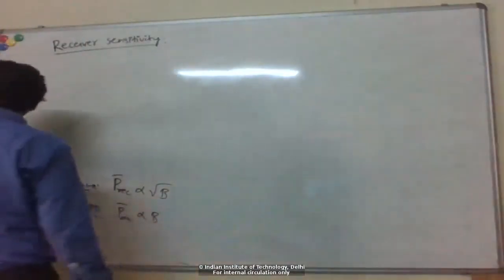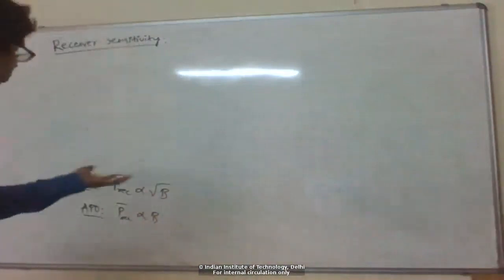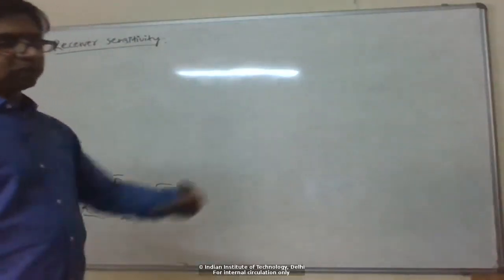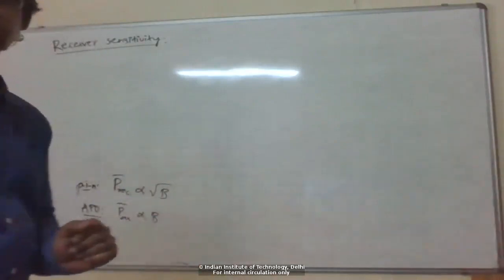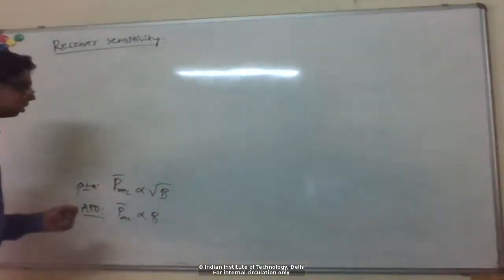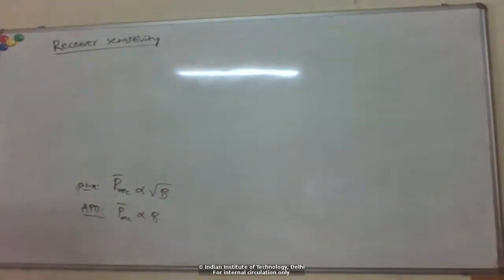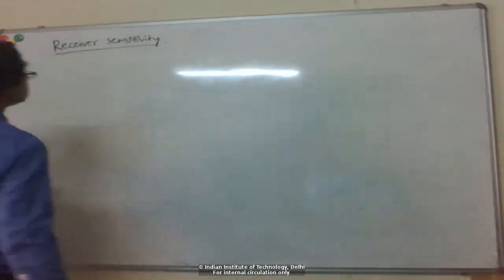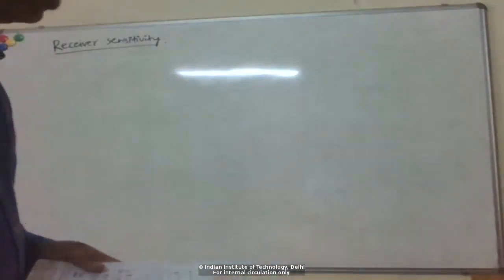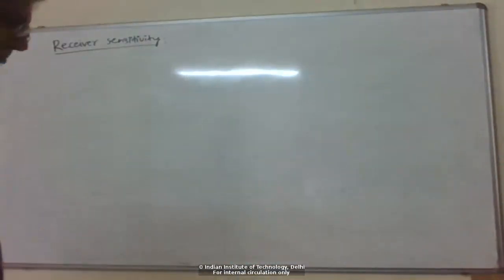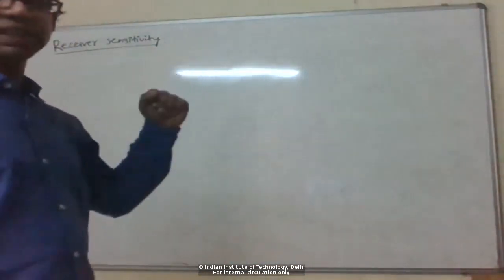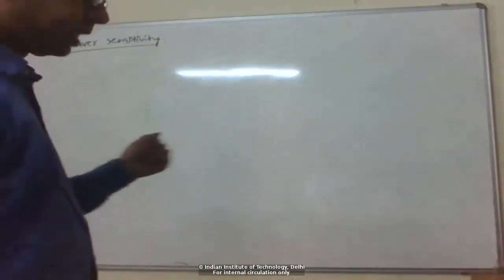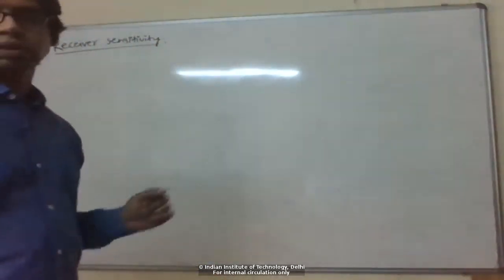So basically this supports our discussion from last time that typically for very high data rates we would go back to using pin photodetectors. But for a given link, based on the parameters of the link, you want to compute these sensitivities for pin and APD in different limits, and then decide for that particular link which might work better for you.